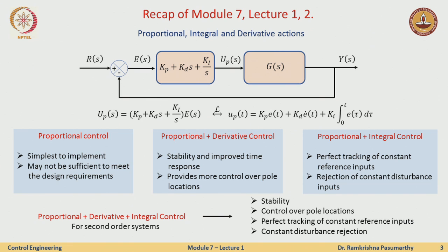Okay. So, what we did so far is, well, just to sum up. So, we had a proportional element, a derivative element, and an integral element. The standard thing is just to be the objective being to track a certain reference at the output. So, well, proportional controller, what we saw was it is very simple to implement, but it may not be able to meet some specifications. Sometimes it is not even good enough to stabilize the system.